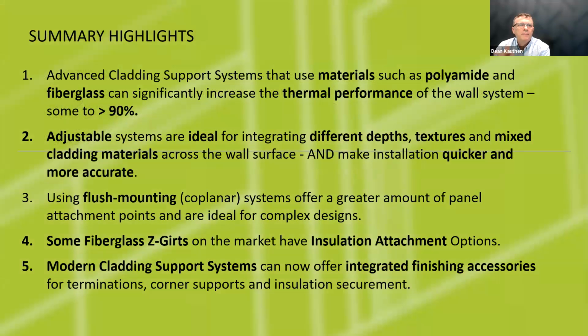And in summary, if we're using cladding support systems like these polyamide and fiberglass materials, they can significantly increase the thermal performance of a wall system. These adjustable systems are available, so you can have different wall cavity depths, you can mix textures and materials, and still have a very cost-effective solution